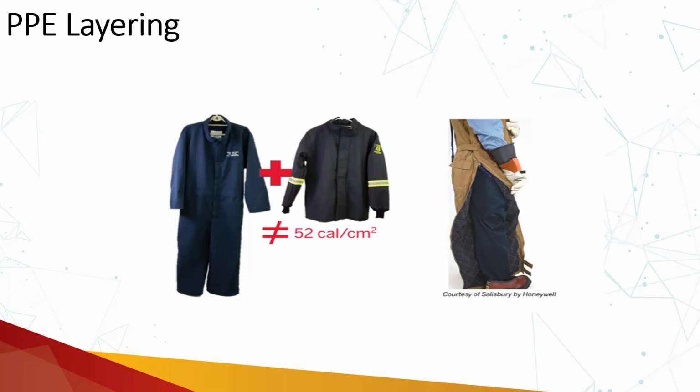But why would you purchase those PPEs and allow your worker to work for that particular level of exposure? Why are you not working to reduce the incident energy at that particular location? Why are you not adopting innovative techniques to increase the distance between the operator and the switchgear itself?